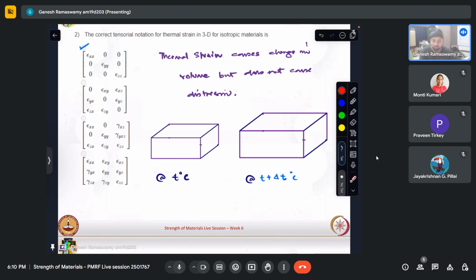Now this is not so in the case of coupled materials. For example, there are materials where normal stresses can cause shear strains, or shear strains can induce normal stresses. So when there is such a coupling between them, then this relation no longer holds. Then that is when the material also becomes more cumbersome to handle. And to characterize such materials, we need to do some additional tests, which is why we are confining our attention to first isotropic materials, where the material properties are the same in every direction. So I hope that is clear. Should there be any questions, please feel free to ask.